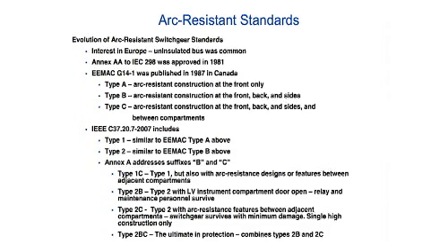All right, this addresses the personnel side of arc mitigation. What about the switchgear itself? If you recall, there was a type C in the original EMAC logic. In C37.20.7, we developed type 2C. It was Annex 2C. In Annex 2C, we said, okay, we're going to have personnel protection, but we're also going to have sustainability of the switchgear itself.